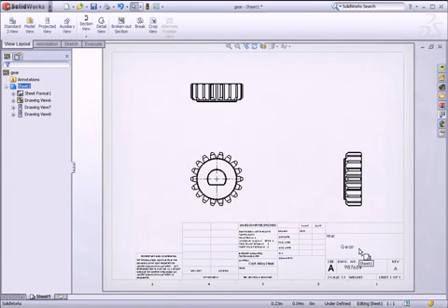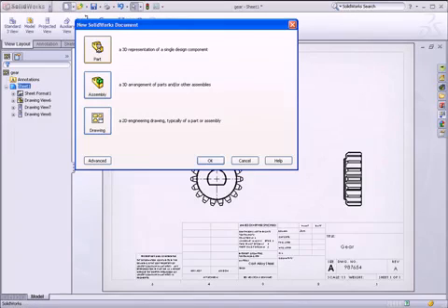This takes a few minutes to set up, but will save you lots of time each time you go to create a drawing. The trick is done with something called Parametric Notes or Smart Notes. The Smart Notes in the title block will work with some properties in the part file, so we'll go through how to create templates for each so they can work together.